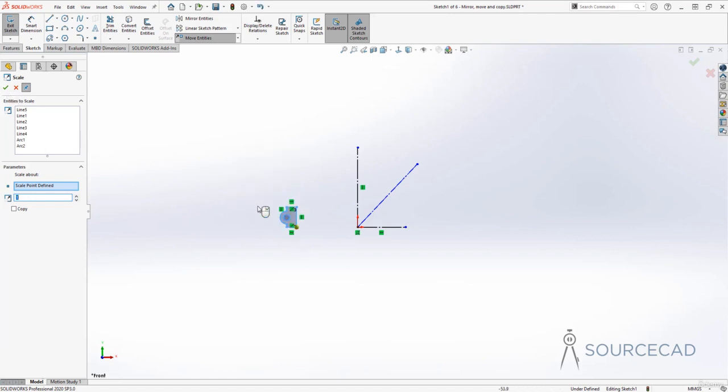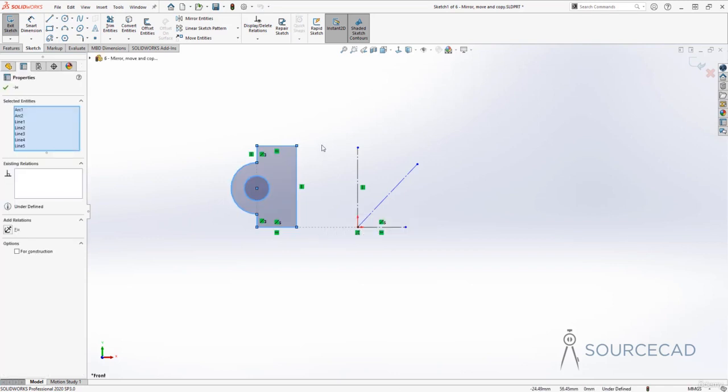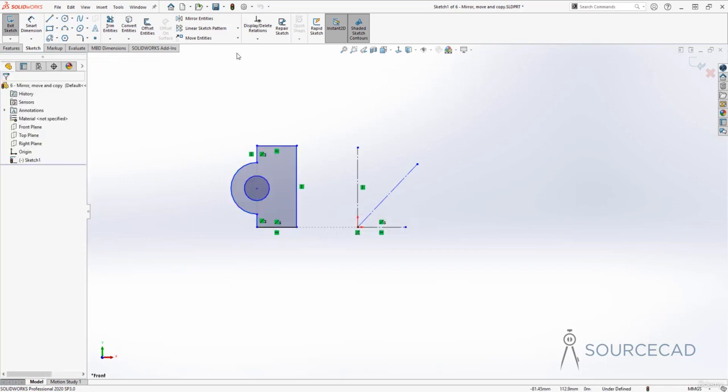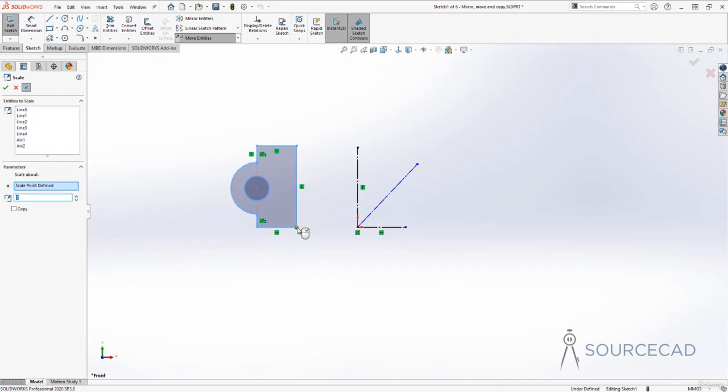That's it. It's 1/4 the original size. Press escape and there we have it. So that's the scale tool. I'll press Ctrl Z and escape and I'll repeat this command. So again, I'll go to scale, I'll select it all, and now base point, maybe again this one, and now I'll keep this copy option checked.